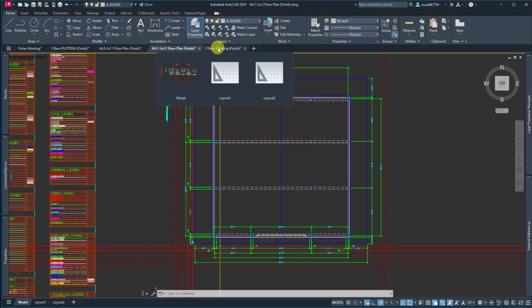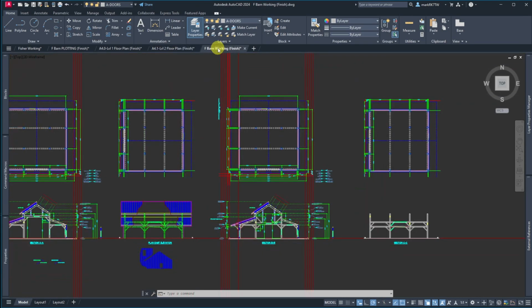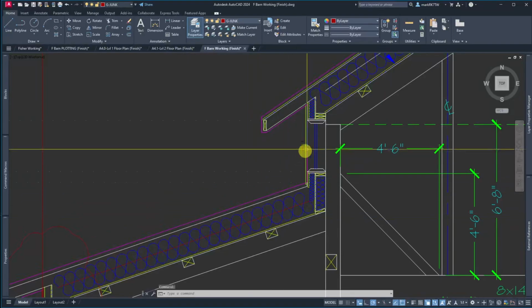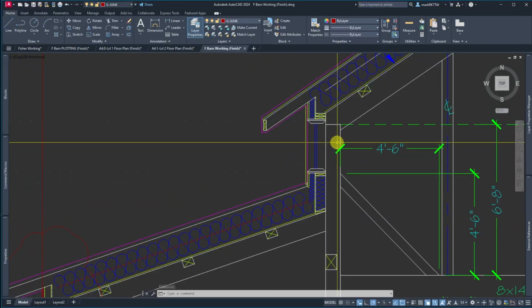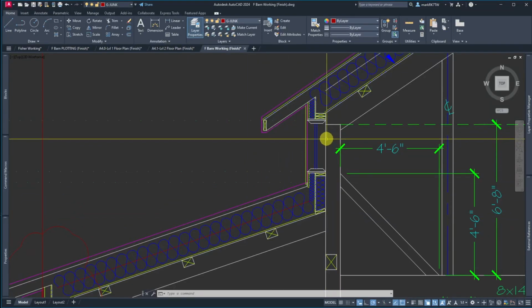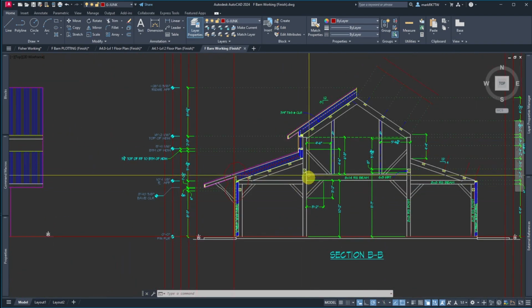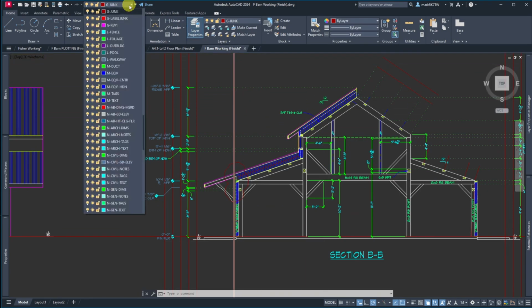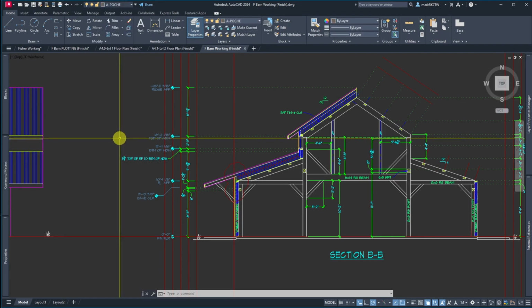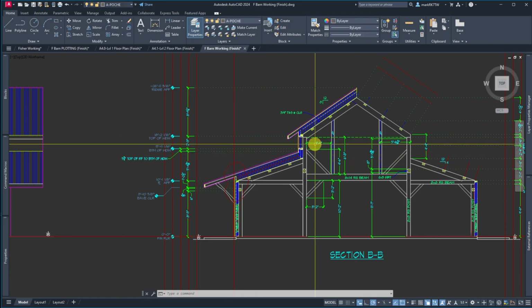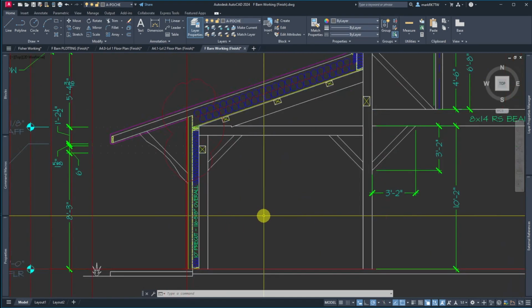And where you see that is, if we go to the working drawing, we look at our section. Here's our post. That's the 8x8 post. One thing that makes these posts really stand out nicely is to hatch them with a poche. So I'll go to my A-poche layer, and that sets up a color that does a real nice halftone when it's plotted with my line styles.